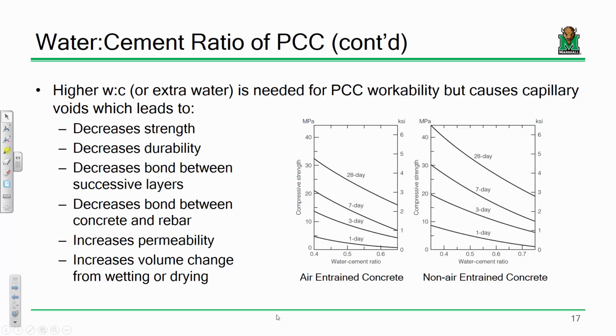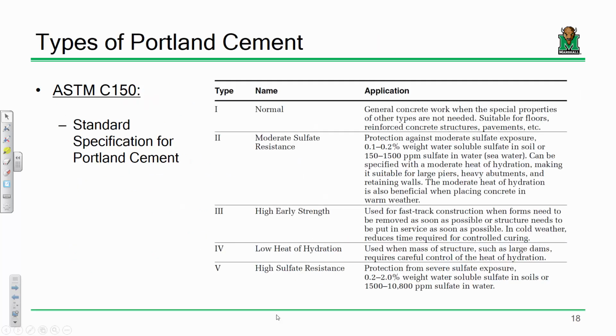One of the last things that we'll do in a mix design is we'll actually correct for moisture within a given mix. Based on an aggregate's present moisture state, we might need to throw in more water, or maybe at the very beginning we were putting too much in and we can actually take some out. That'll make a little more sense when we actually get into concrete mix design.